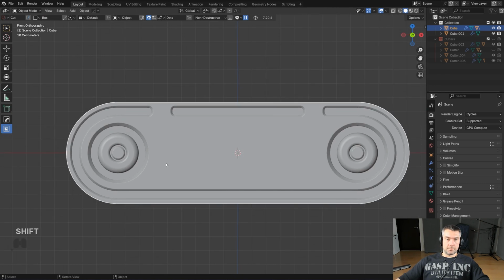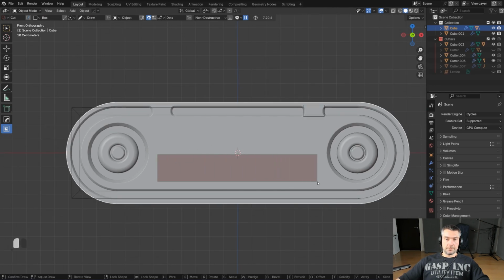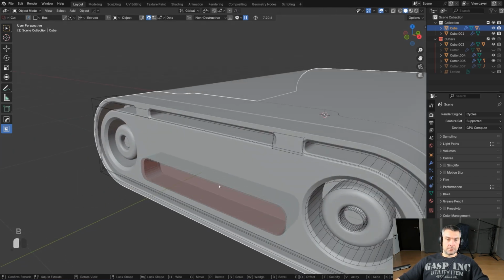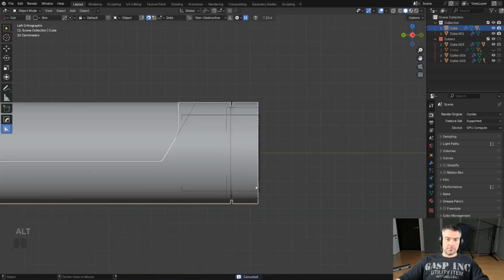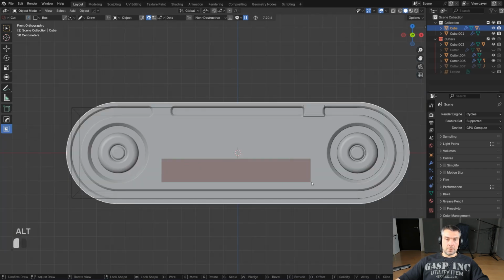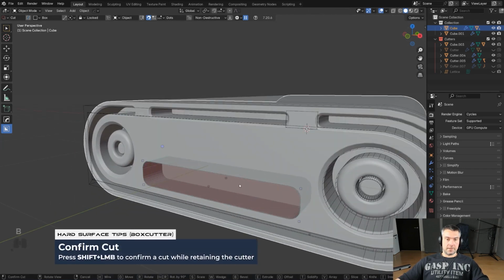We could run a cut in the bottom, so we're going to offset from the top. Larger cut here. If you want to make the same size of cut as in the top, it's going to look a bit weird, so you want to make it a bit larger so it looks better. Press B for bevel, and we're going to drop it in one more time. Okay, bevel, there we go, drop it in. And then shift click.